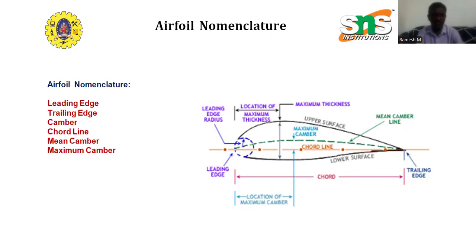It's where the air recombines after passing over the airfoil. Shapes and angles at the trailing edge influence lift, drag, and other aerodynamic properties. Situated at the rear of the airfoil, the trailing edge represents the point at which the airflow over the upper surface converges with the airflow over the lower surface. The design of this portion of the airfoil is just as vital as that of the leading edge. Its purpose is to ensure that the two airflows meet with minimal turbulence.